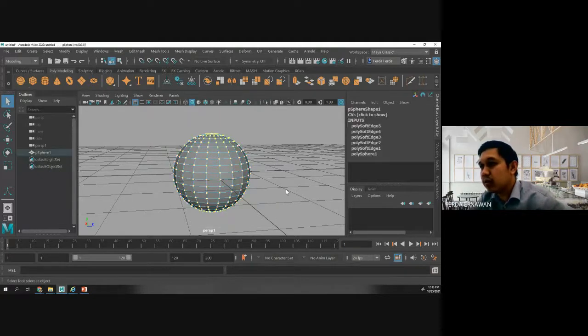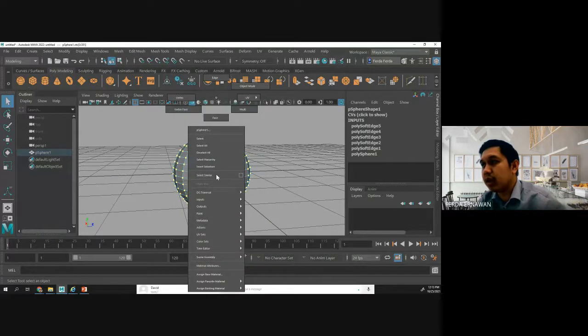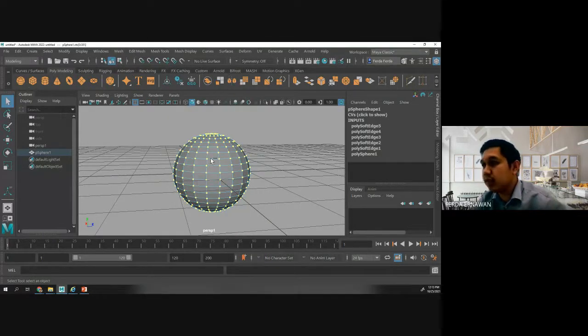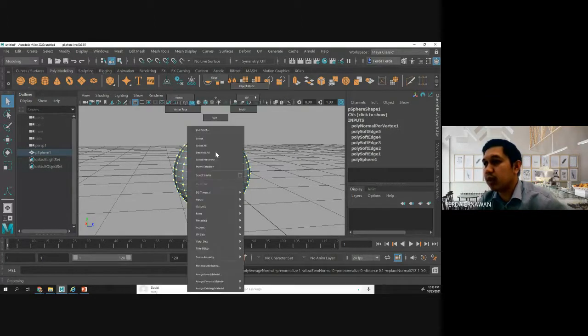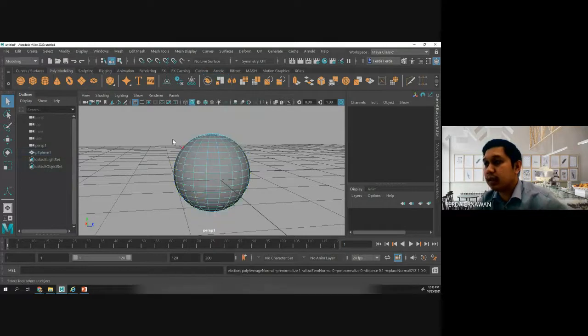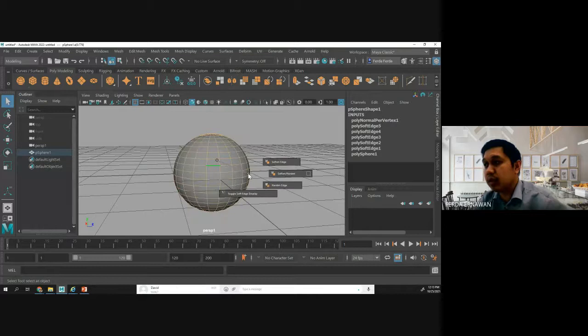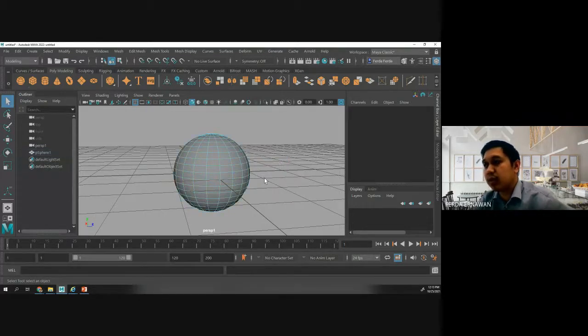Now I'm going to make this one smooth object as a normal one. So I have to Shift again, right click, vertex normal, not vertex, edges, right? Select all. I want to return back to the normal one, so I will make it the soften edges for all. If you go to the object again, you can see it becomes smooth as the original.